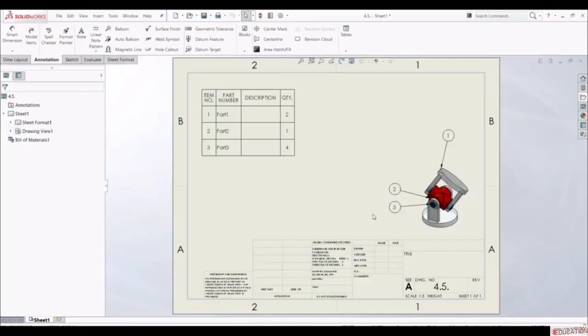In this lecture, we're gonna show how we can use equations in the bill of material table. Equations allow us to do simple calculations and simple functions. So with equations, we can multiply, subtract, or add different properties. As well, for example, we can find what is the overall cost of the assembly, what is the most expensive part, or something like this.